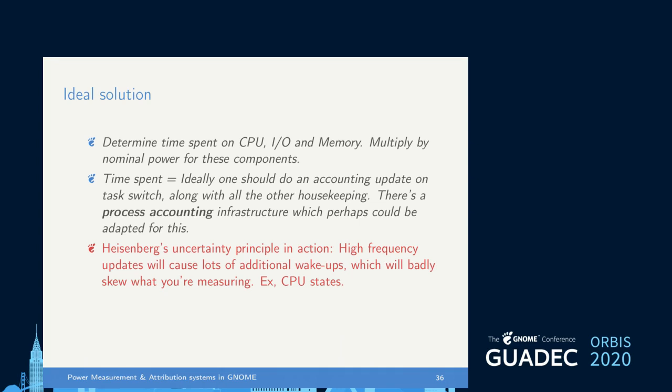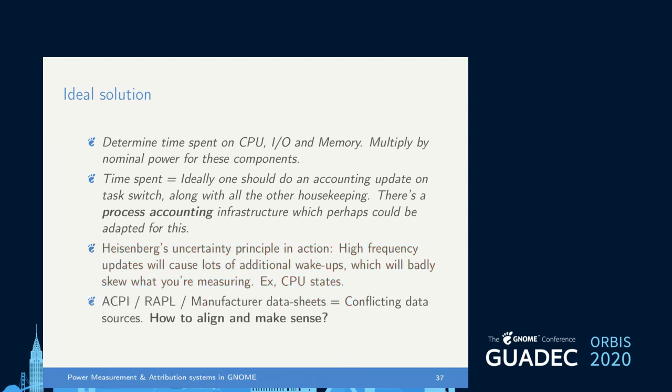And it wakes up and says, hey, I'm using 10 watts right now. So this is skewing your measurement completely, right? You don't get the right number in the first place. The right way to get this is using an observer probe, using a current and a voltage probe, and actually getting that value in an oscilloscope. But we can't expect our users to have oscilloscopes dragging around with their systems, right?